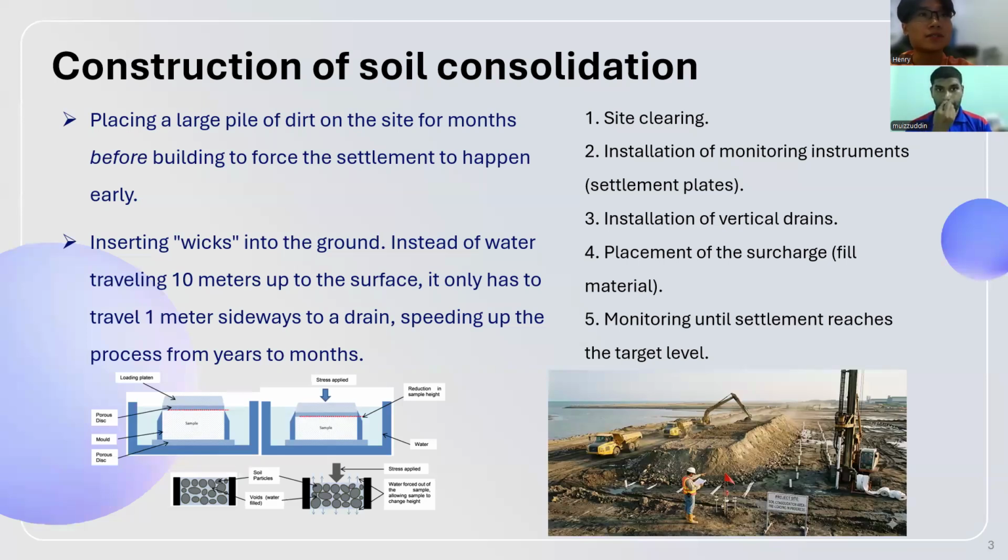The next is inserting bricks into the ground. Instead of water traveling 10 meters up to the surface, it only has to travel 1 meter sideways to a drain, speeding up the process from years to months.